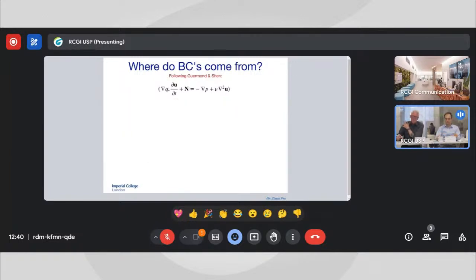So this gives us our last step. This was the building block of Gaumond and Chen. Through realizing that bit of analysis, they said, well, doing all that integration by parts, it's almost equivalent to something that looks like my Navier-Stokes equations. Here is how we'd normally have written this, the divergence of the Navier-Stokes equations. So this looks like the pressure Poisson system, but plus a lot of terms that actually need to exist on the boundary for it to be equivalent. And this is my pressure boundary condition that's come out of this.